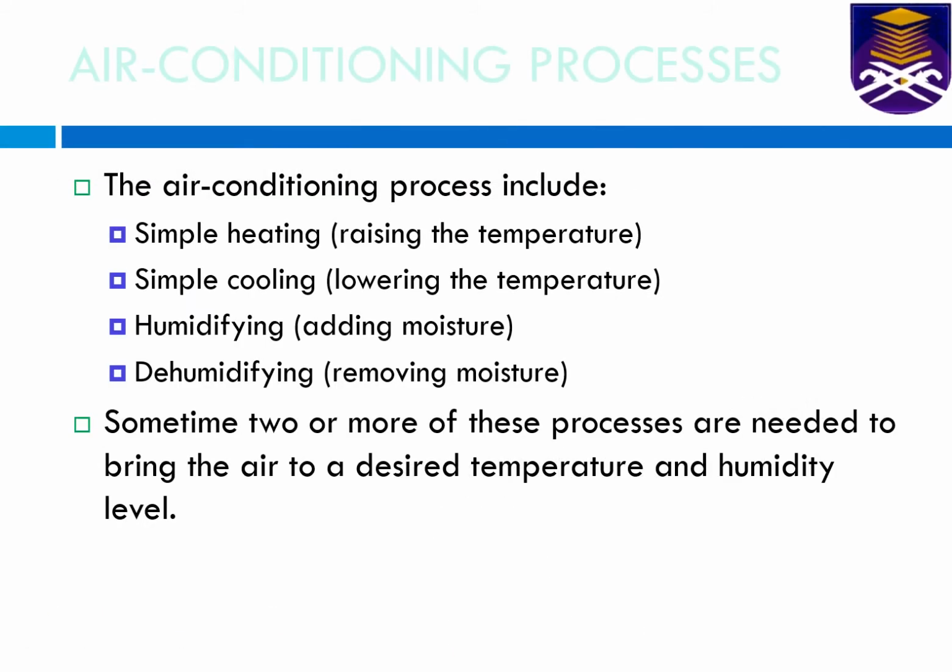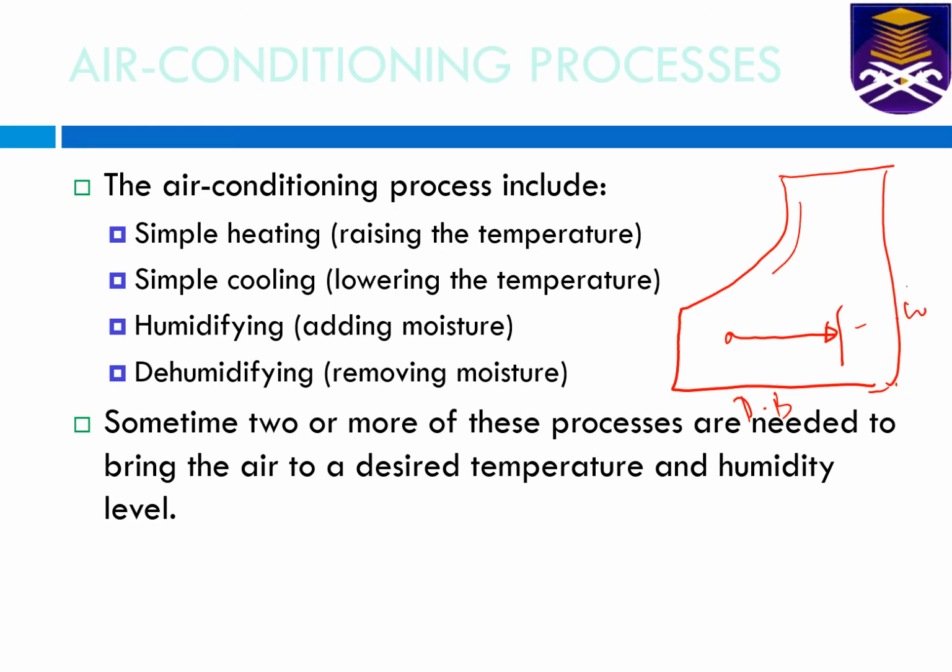Imagine this is a simple psychrometric chart. This is the dry bulb temperature. Moving from left to right is simple heating, and from right to left is simple cooling.